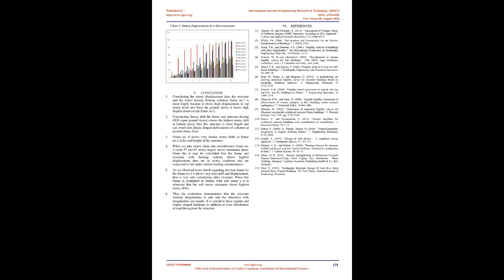When this frame is compared to frames with soft stories, it is observed that the soft story structures show the highest story drifts. 6. Thus the evaluation demonstrates that the structure without irregularities is safe and the structures with irregularities are unsafe. It is crucial to have regular and simple shaped buildings in addition to even distribution of load throughout the structure.